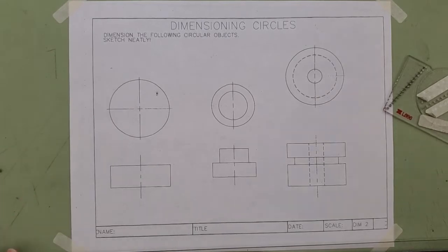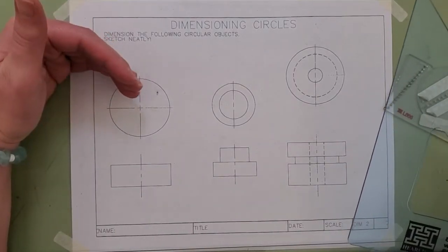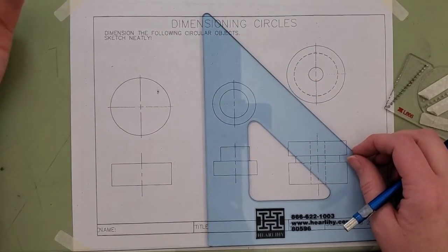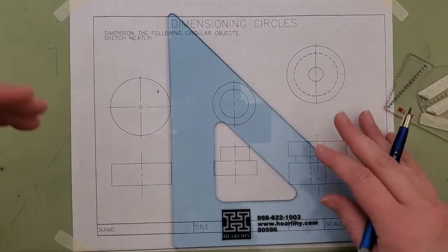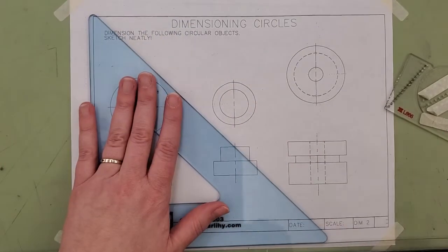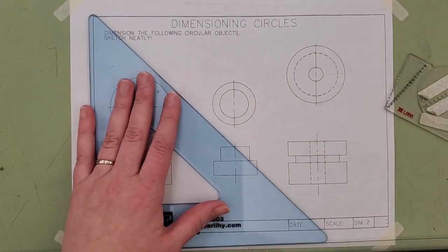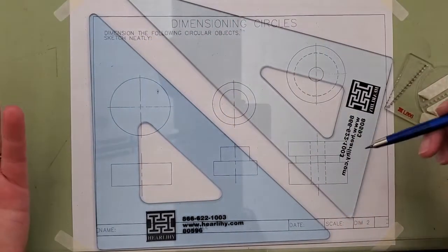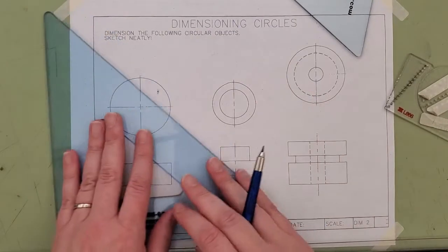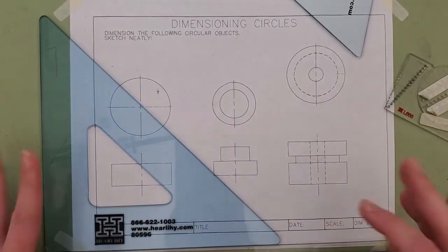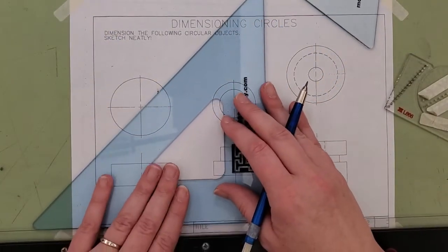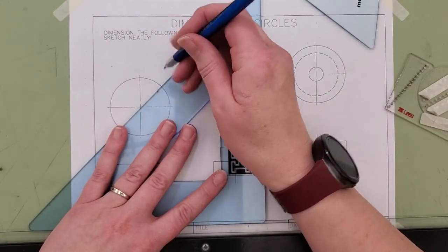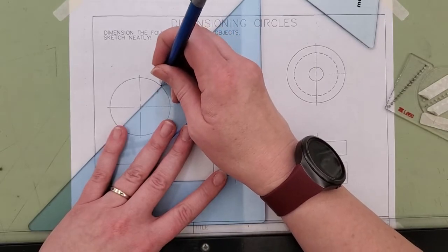And what these are meant to do is lead your eyes to the round surface, okay? That's a hard cut to make, and drill size and location are very important. So we're going to use something called a leader line. Now, we can use the three most common angles, 45, 30, and 60 degrees. But you can make the leader lines at almost any angle that you wish. The trick is you're going to be wanting it to point directly to the center point, but what's going to happen is